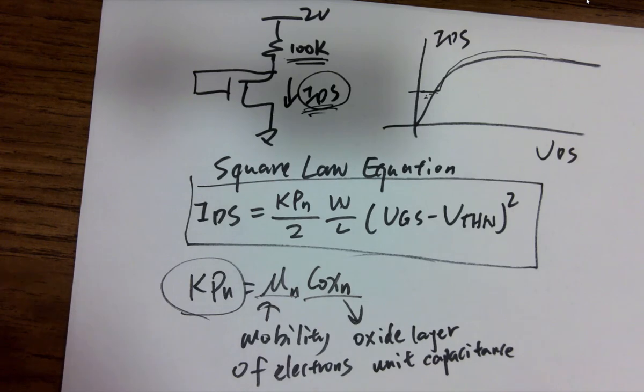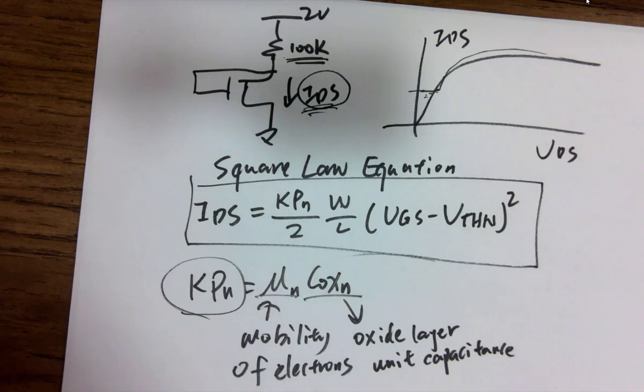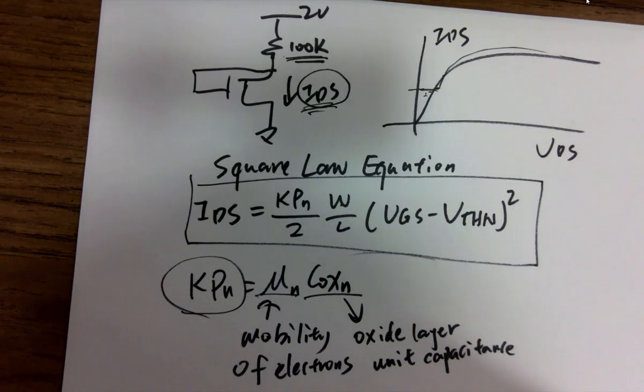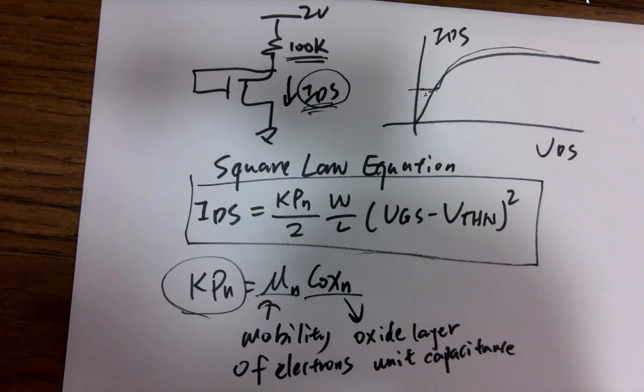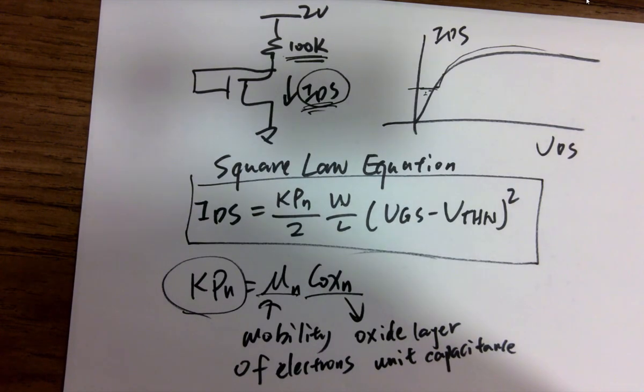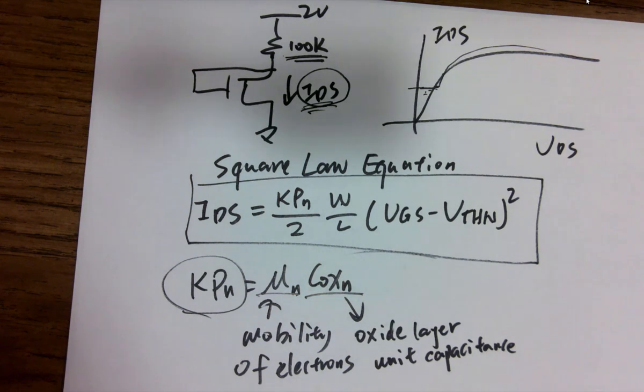So we're going to keep the minimum length and then modify the width to modify the current. What about changing both at the same time? They cancel out each other. It's a ratio, and you are increasing the dimension, the footprint of the chip, making no sense. The goal of having smaller and smaller nodes, and smaller technology, is to let us use a smaller length. If you increase the width at the same time, you're wasting money, right?